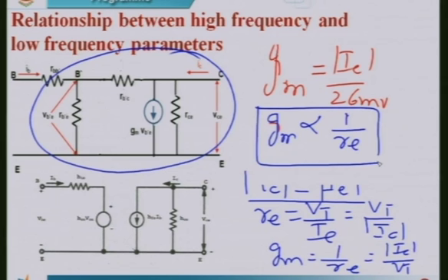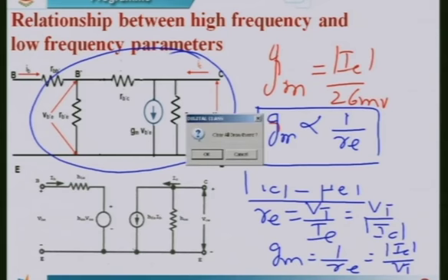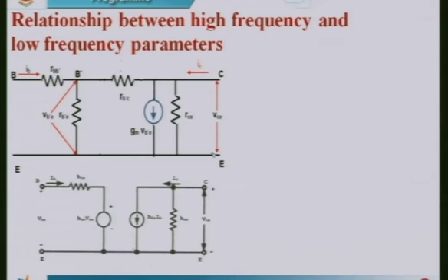Next point is, what is the relation between the input resistance rb'e and the input resistance hie? We need to find the relationship between the input conductance or the input resistance, given by rb'e, or we can also find 1 by gb'e. Already we know that at mid frequency the capacitance Ce is negligible.